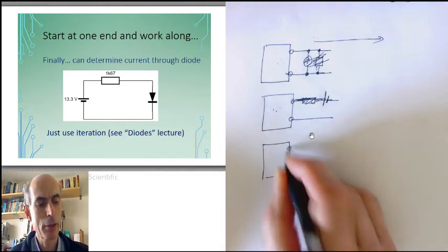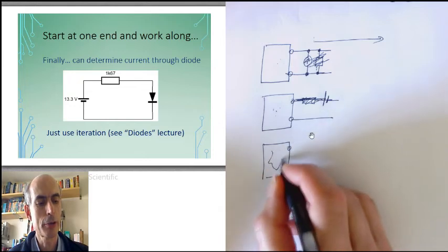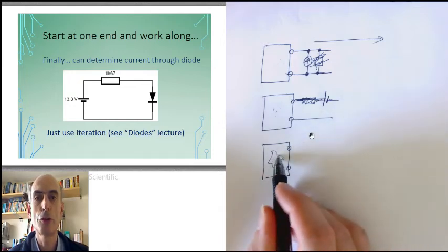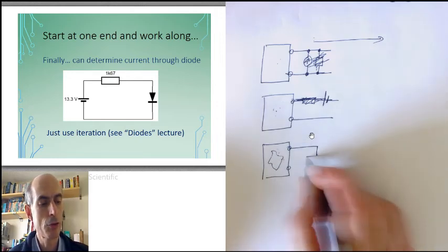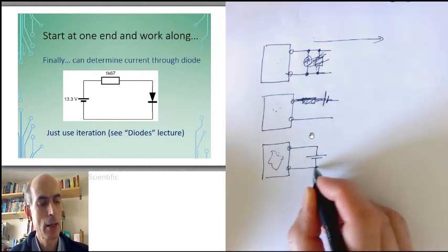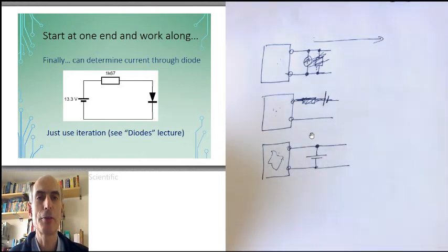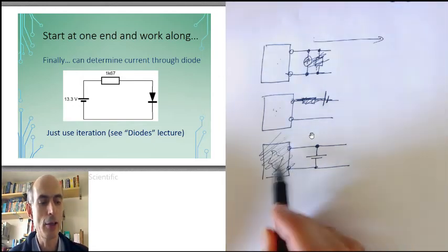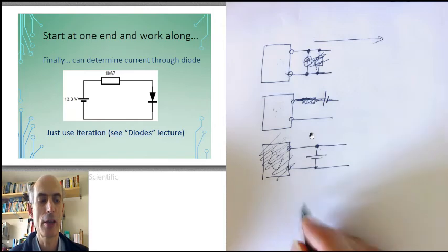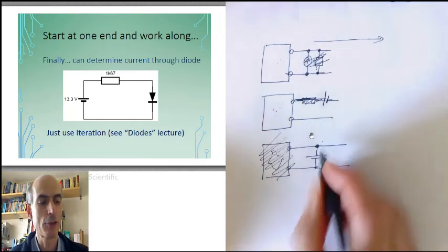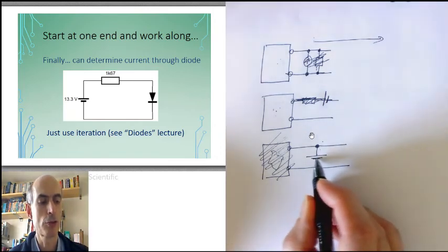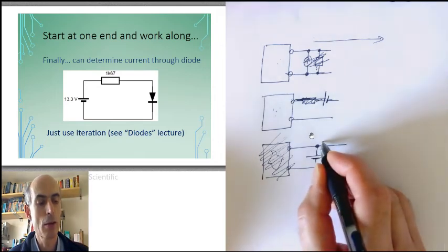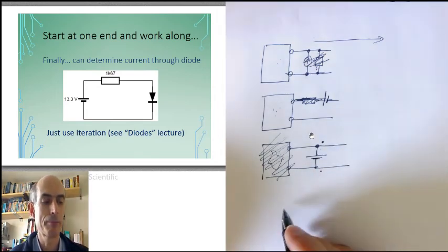Occasionally, you might find circuits with a large number of components here, which you've reduced down to a Thevenin or Norton equivalent. And then there is a voltage source on the circuit like this, at which point you go, darn, I've been wasting my time. I didn't need to analyze any of that stuff. I could have just started here and said that the voltage is whatever the voltage source enforces. The voltage here would be just that voltage above here.